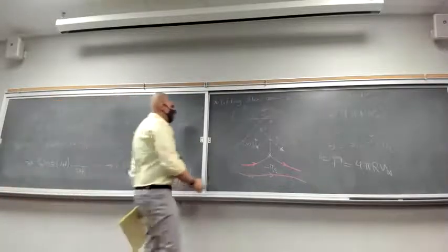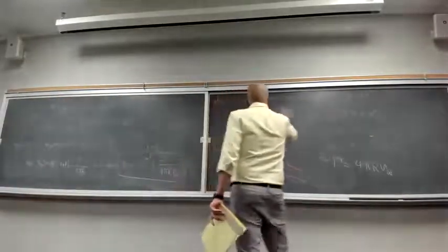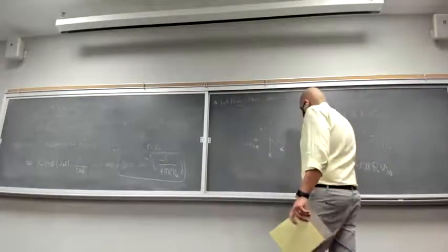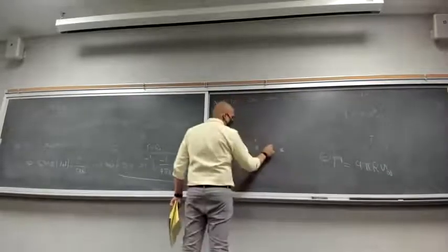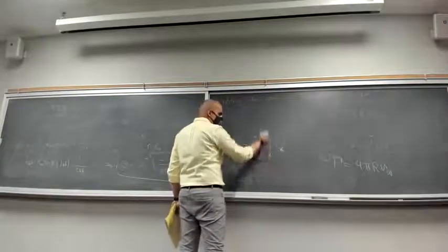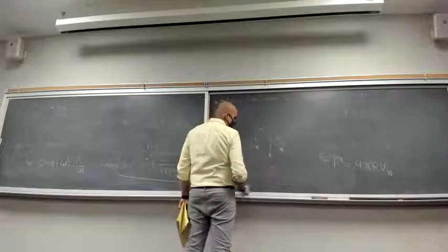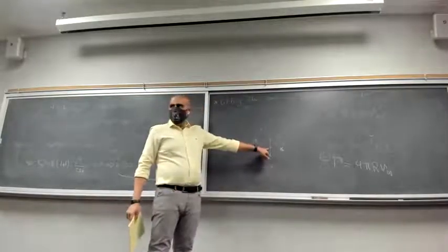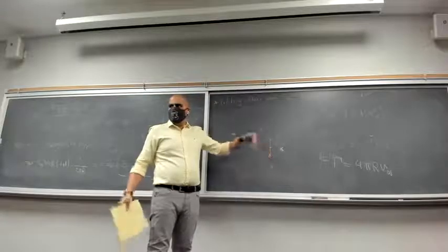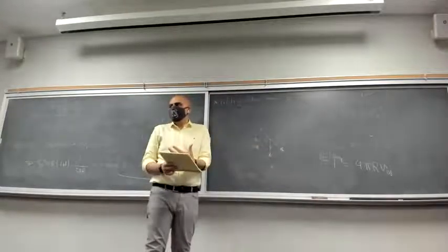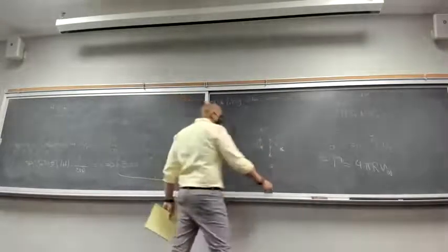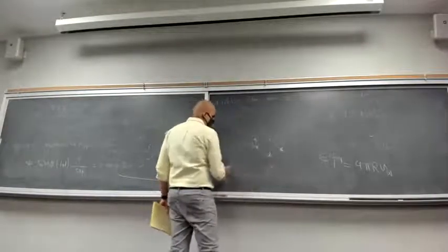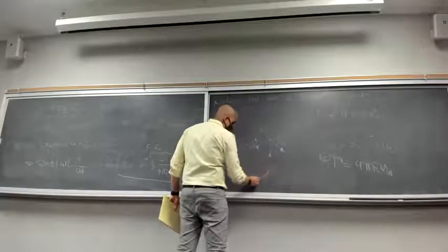So your mathematical stagnation points are going to be one inside the circle on the pi over 2 line and one outside, right? This is an illogical, irrational solution because there is no flow inside the circle. So we can just dump this solution and get the new stagnation point.